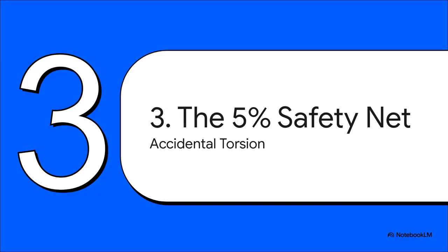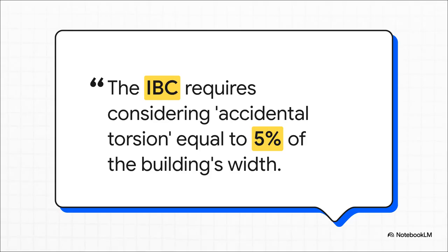But let's be real. In the real world, no building is perfectly symmetrical. So how does the building code deal with this? Well, it uses this really clever safety net. The International Building Code is pretty smart about this. It knows that even if a design looks perfect on paper, there are always going to be tiny imperfections in the real world, in the materials, in the construction. So it makes us plan for something called accidental torsion.